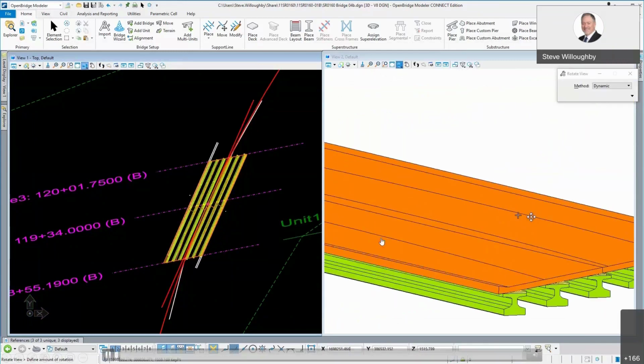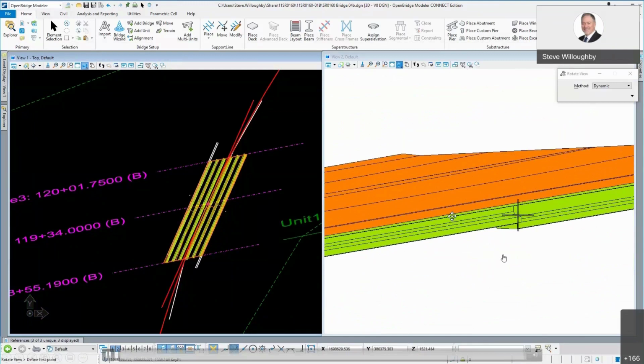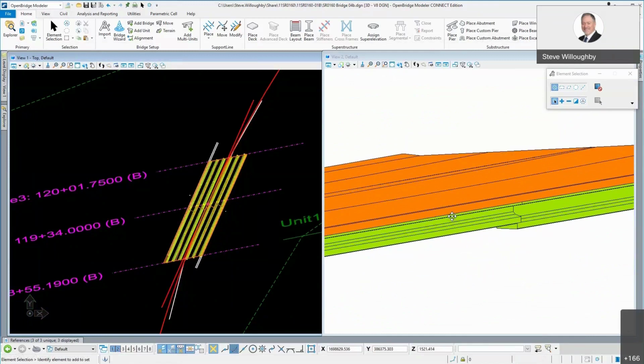Now at this point, the one thing I didn't do in these particular videos is create, let's say, some piers and abutments that were only for stage 2 and stage 3, but there's no reason you couldn't do that. The only trick there, honestly, would probably be just the understanding that in our abutment library and pier library, the key point on the top of those is at the center of the cap, transversely.